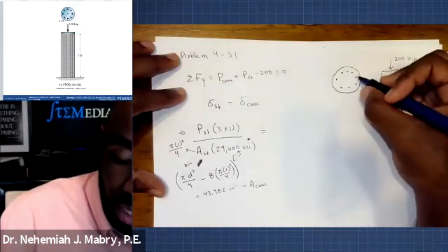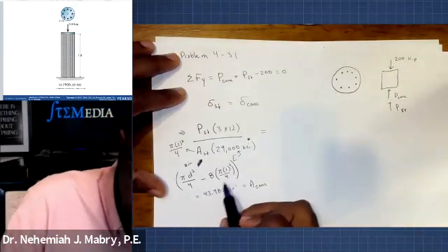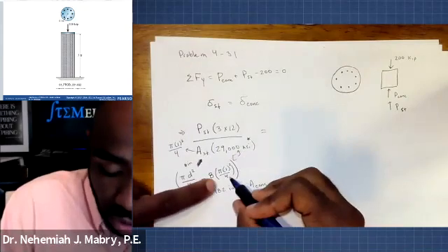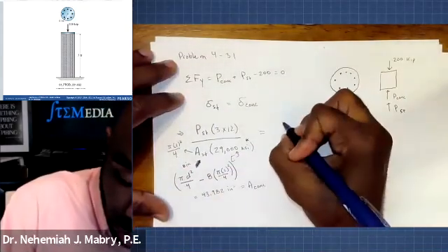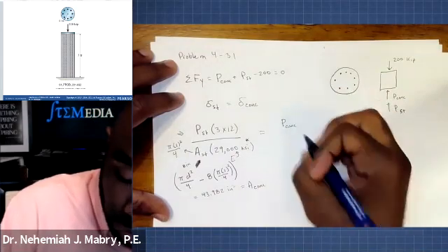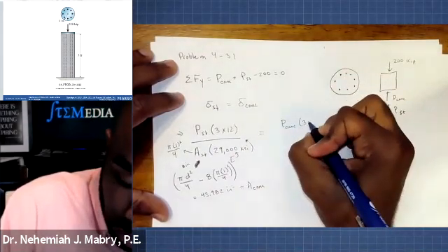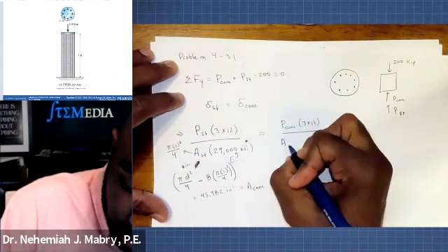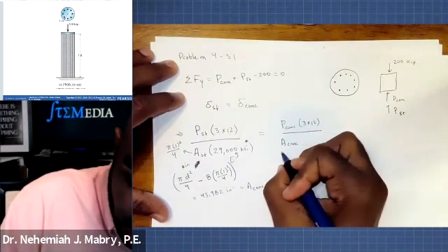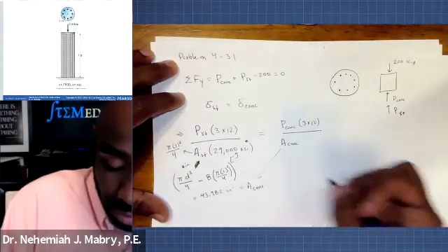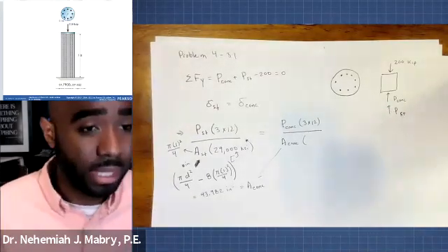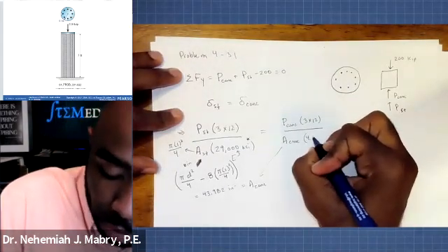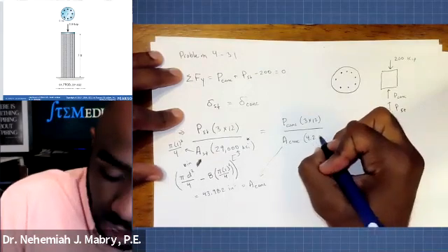All right, as I just explained here, I gave you the cross-sectional area, then I subtracted the area of the steel. I lost track that this side is looking at the area of the steel, which is just this part. So this comes over here. So P concrete times the length, 3 times 12, over the area of the concrete. And that is what we calculated here. The area of the concrete times the elastic modulus of the concrete. Now this will vary a little bit for this particular problem. The answer is 4.2 times 10 to the third.